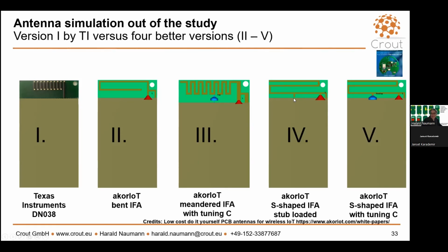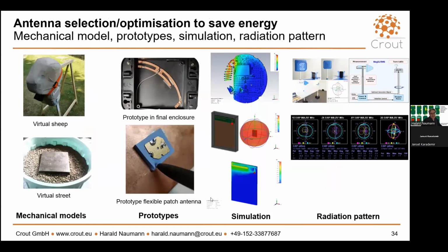So I told my team I would like to have the 0 ohm antenna, so I have a perfect 50 ohm at the feeding point without a matching. And we use this small capacitor as a parasitic element here to optimize the 50 ohm as well. And here it's the same as here, but the difference is that we have a real capacitor in, and we change between 2 capacitors and can then change between 915 megahertz and 860 megahertz.